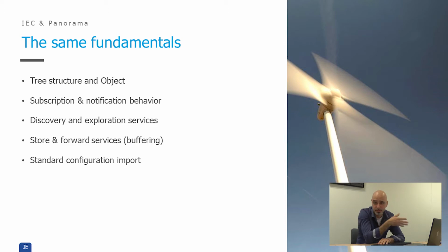So I'm not especially talking about 61850 for this purpose, but also about Panorama with existing features not especially developed for this purpose, but the mindset is the same, explaining the behavior of the electrical installation, and at the end using this behavior, this template structure in your Scada applications is the easiest way to handle the specification of the installation through the entire project, from one end to the other end. So you will find exactly the same information at the end in the Scada behavior as specified in your 61850 approach.